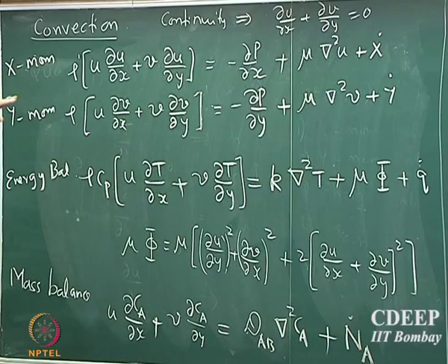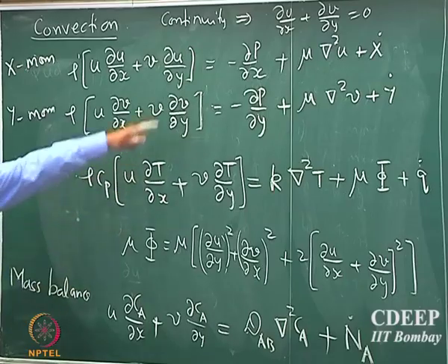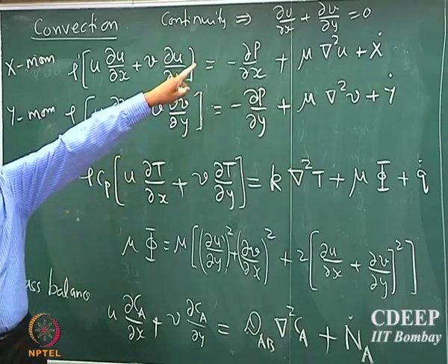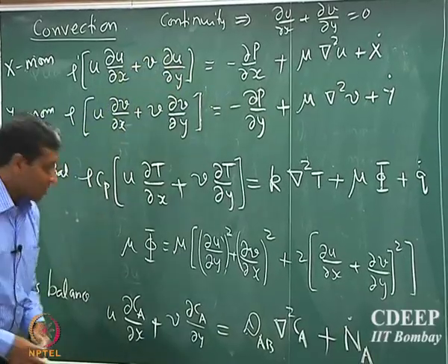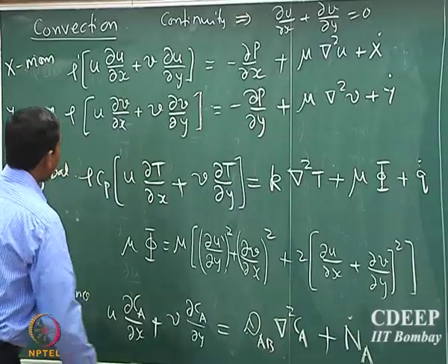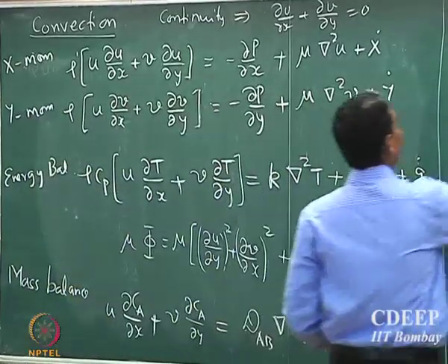So we really don't have to solve the continuity equation because the fluid is incompressible and it's a steady state system. We are looking at a steady state incompressible fluid, so the continuity equation will always be satisfied. You don't have to worry about solving it. Okay. So all we will have to worry about is solving these four equations.